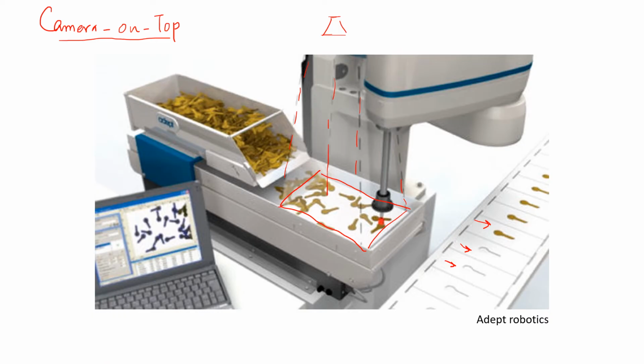So it is not the space to further dig into how we're going to achieve that, but generally in this particular paradigm there are certain issues. And one of the issues is that when camera is on top, and if the robotic arm is hindering the view, then it is the occlusion problem that you're going to observe. So view is going to be occluded. But the benefit is that because the camera is fixed, it is on top, it is observing the same rectangular field of view, so it is not going to require any recalibration or reorientation or re-registration of the images. So in that sense, it is going to be kind of a fixed field of view which is needed to be handled. So that is one good thing to have.